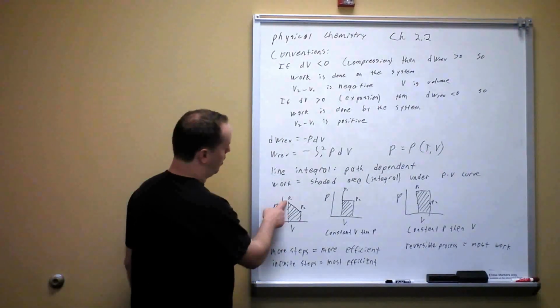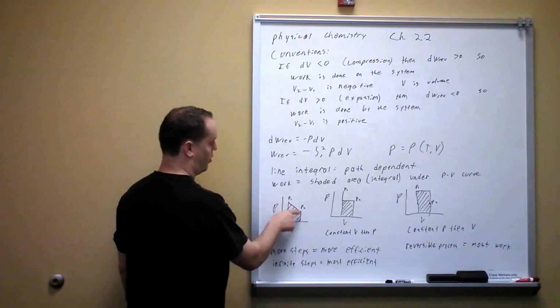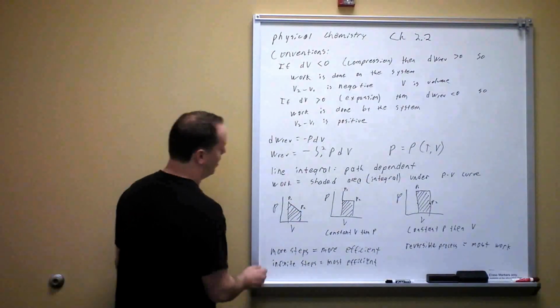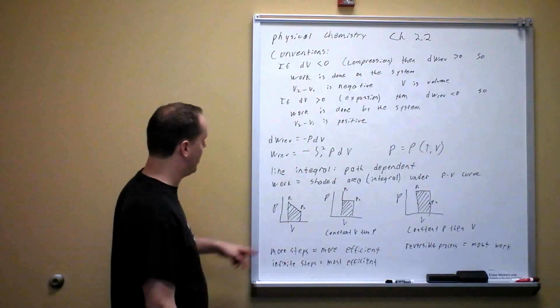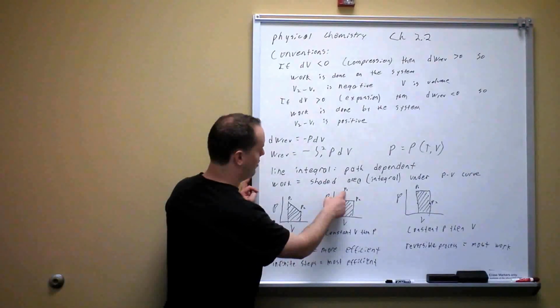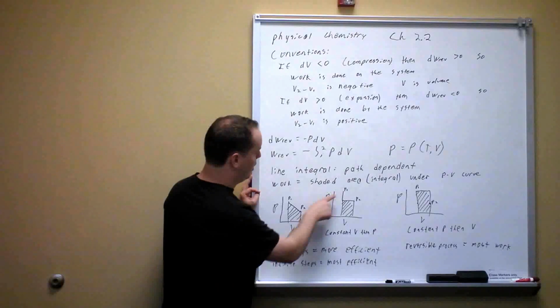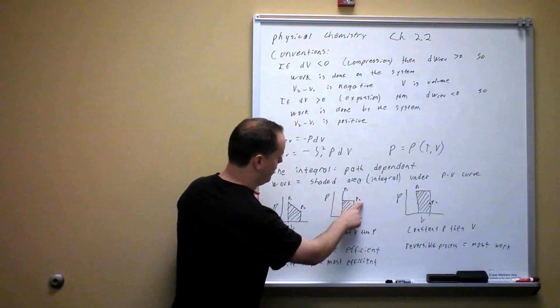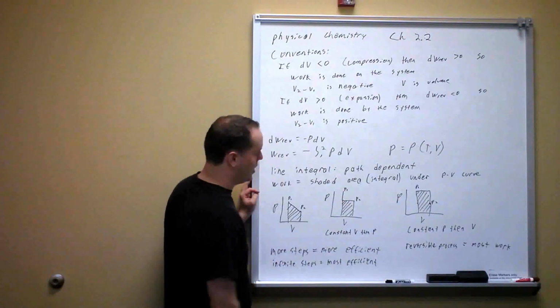We're going from state 1 to state 2 here. We're changing both pressure and volume. Notice we're going in a roughly straight line, and the area is going to be this shaded here. So that's the amount of work being done. Now let's say that we're going from the same state 1 to state 2. I didn't draw this to scale, obviously. But this time we're going to go constant volume and then constant pressure. As you can see, our work went down because we're only shading this much.